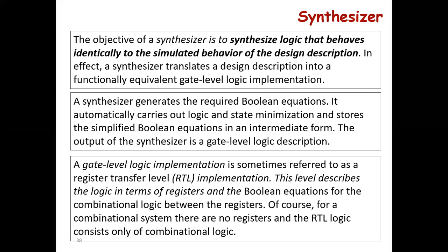Next one is the synthesizer. The objective of a synthesizer is to synthesize logic that behaves identically to the simulated behavior of the design description. In effect, a synthesizer translates a design description into a functionally equivalent gate level logic implementation.